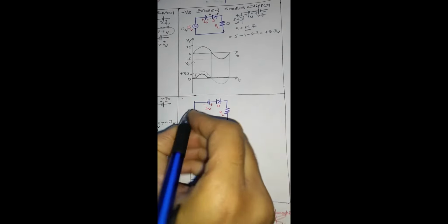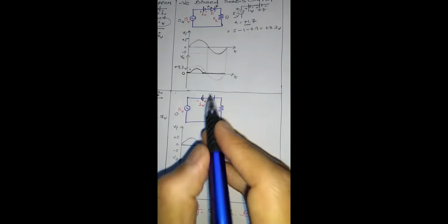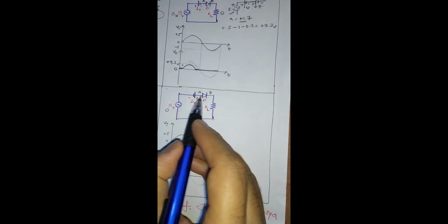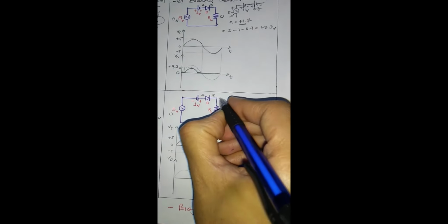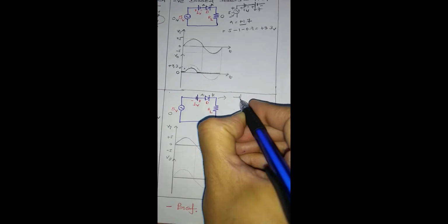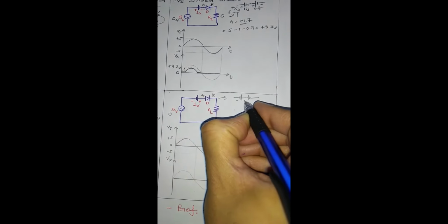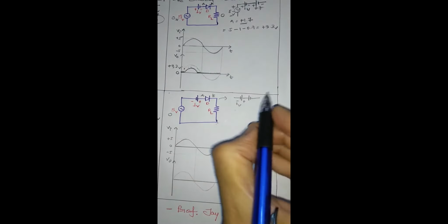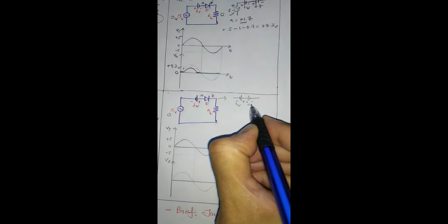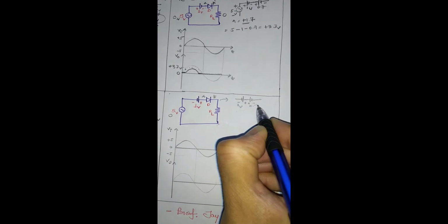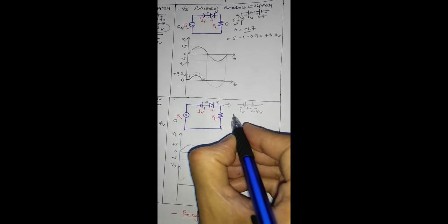So in the next configuration, initially, same as before, consider input equal to 0, then think about the bias voltage. So definitely first of all, anode and cathode. So D is on, then draw the equivalent diagram. So the equivalent diagram of bias and diode. So plus minus 1 volt and plus minus diode voltage, which means the diode is on.